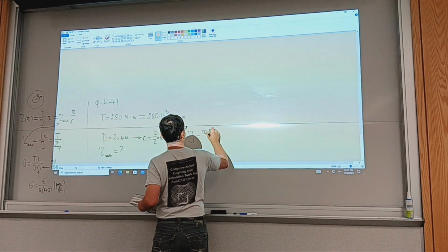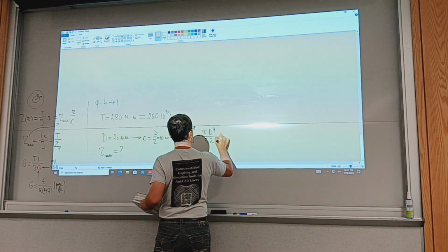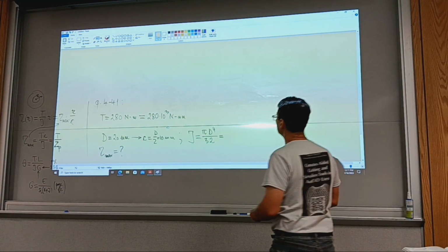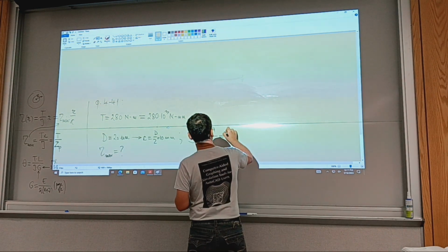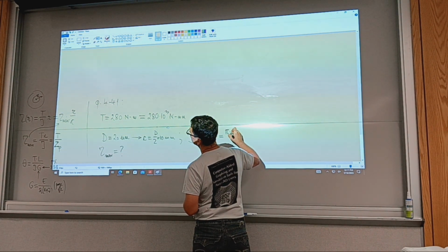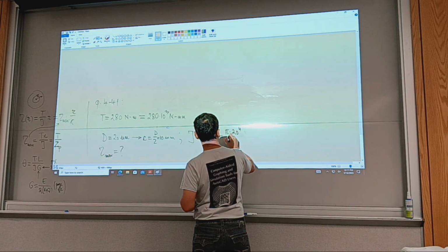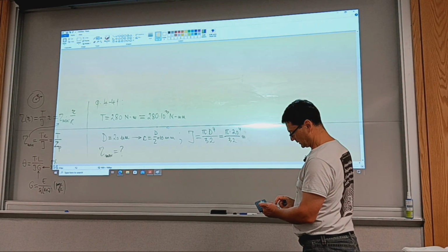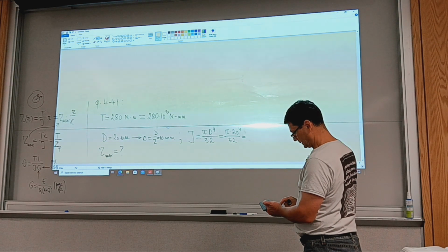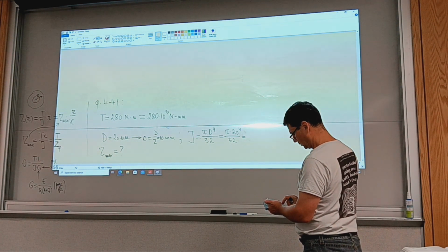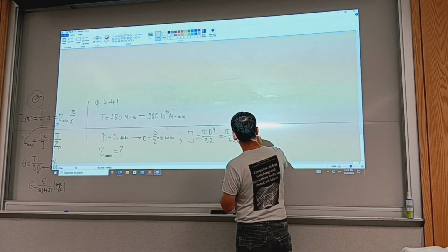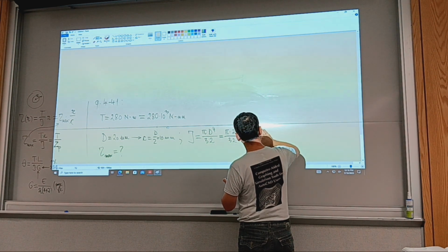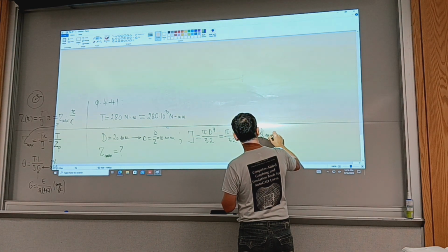So we can calculate the polar moment of inertia in millimeters to the power 4: pi times 20 to the power 4 over 32, and we get 15707.96 millimeters to the power 4. I need to put it in the memory.